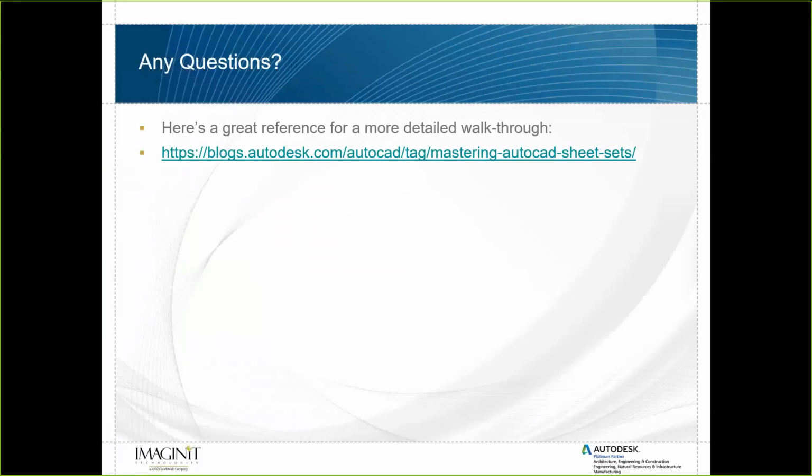So had some issues with VPN and sheet sets, major delays and lags, resorted to closing sheet sets to do work until back on local LAN. The more drawings and more sheets, the worse it is. Is there a solution for this? Perhaps Vault? No, because you're working over a VPN, what you're doing when you have the sheet set manager open, and you have not closed out of it, is you're actually keeping a tab on every single one of your drawings that's in that sheet set.